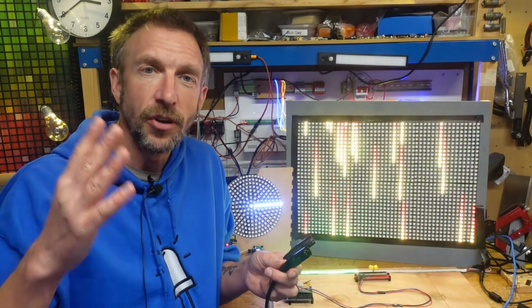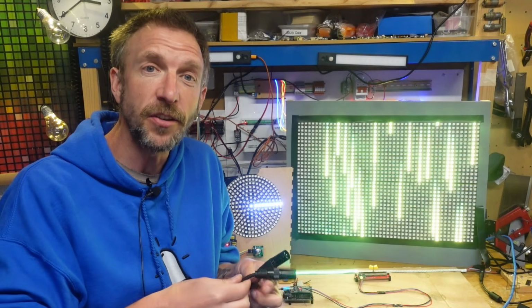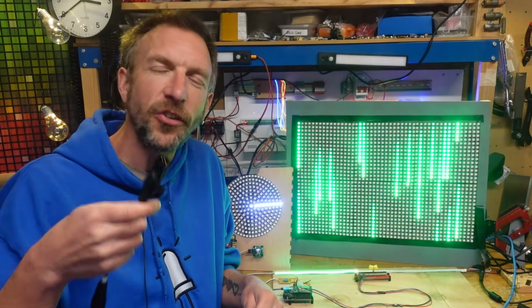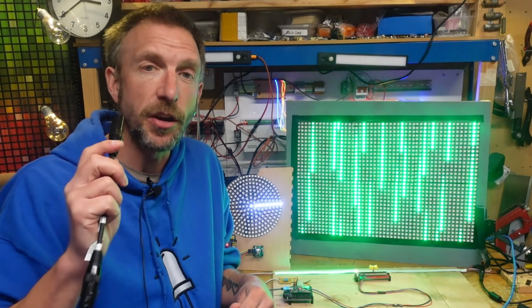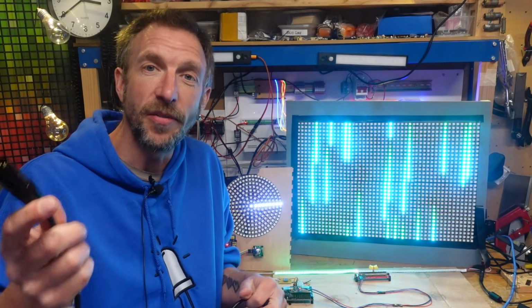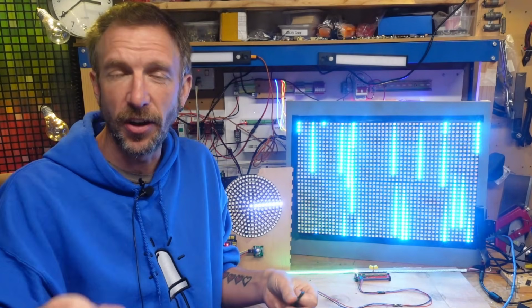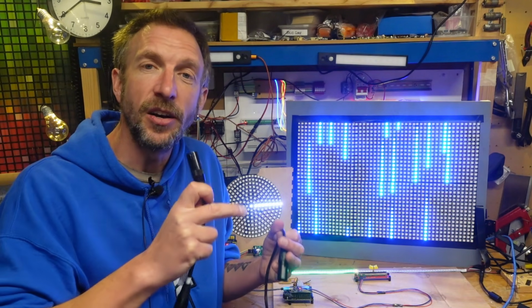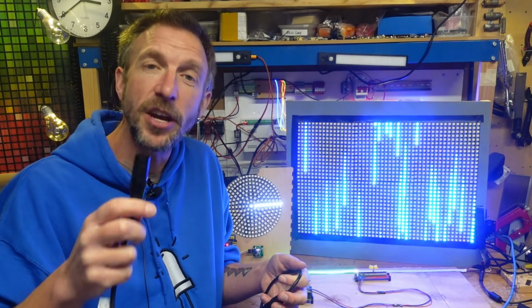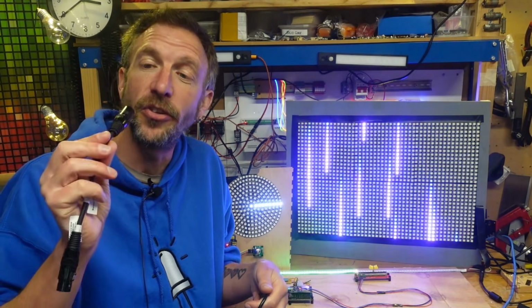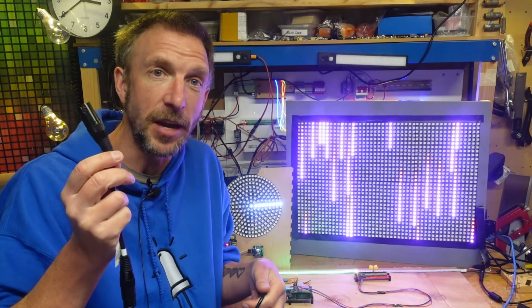Now, all of your lighting fixtures are connected in series using physical daisy chain wiring. So if you're controlling something like a DMX spotlight that only requires a single channel of data to control its brightness, with a value of 0 being off and 255 being maximum on, and all the values in between are increasing levels of brightness, you could control 512 of those spotlight fixtures using a single universe of DMX.